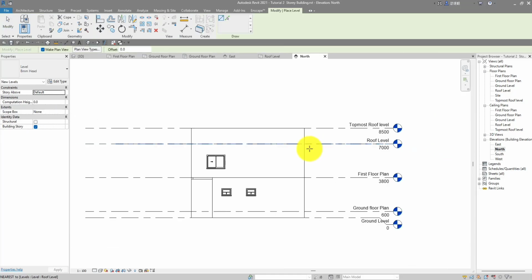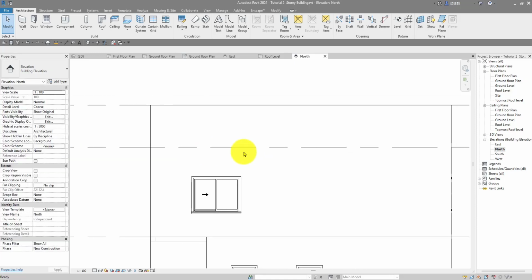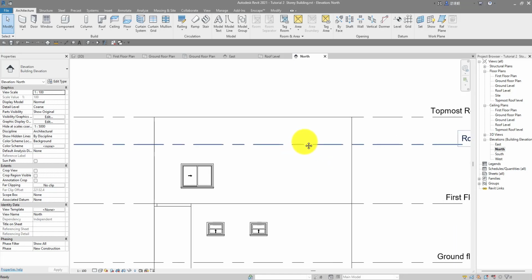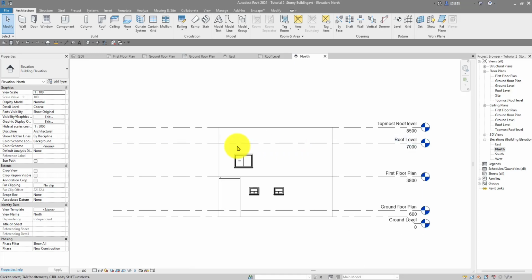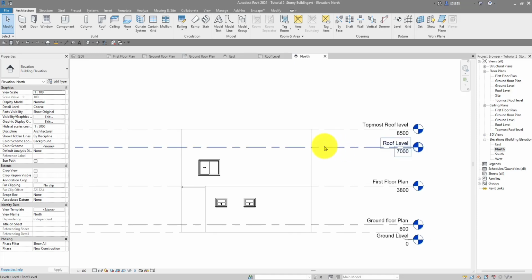Now in creating a parapet roof, you would have to get a wall, alright? You would have to get a wall going up on the roof level about 450 mm, going high above. In case there should be rainfall, it wouldn't slip under the roof and enter into the space we have in there. So we have to lift up a wall, alright?